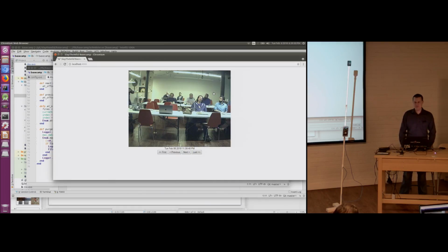You're using Nerves UART. I noticed you're using passive mode. When I've used it in the past, I've experimented with active versus passive, and it seems like active might be good here. Have you tried that? I haven't tried active. I'm trying to think why I was using passive. With passive, I'm doing multiple reads and buffering the image. In active mode, I would have to publish those out somewhere and store the buffer internally. It'd be doable, but passive was simple enough to just continuously do the reads, buffer the image, and then when you read the last bytes, write it out and clear the buffer. Cool.